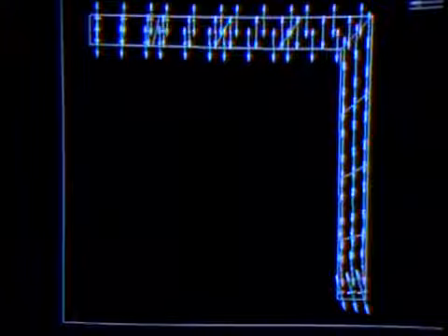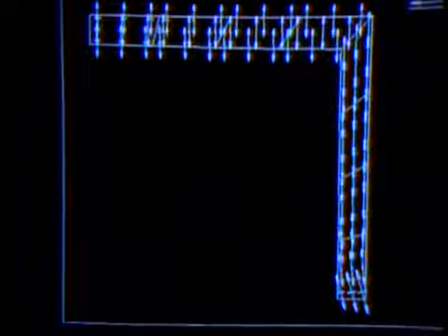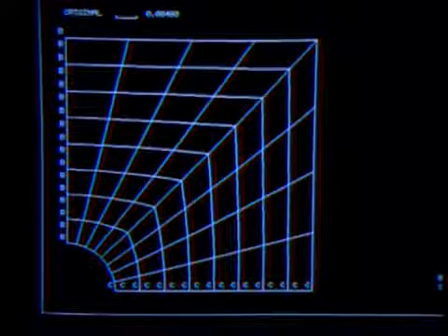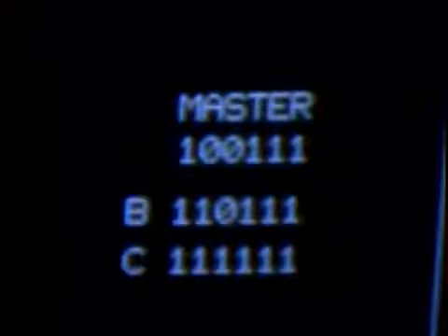Next, we show the stress vectors in the outermost elements of the quarter plate, and we can see here a stress acting perpendicular to the free edge of the plate when we look near the horizontal symmetry line. This is also unphysical and is due to having specified the wrong boundary conditions on the horizontal symmetry line. The specification of the boundary conditions is shown here. The character C denotes the boundary condition on the horizontal symmetry line. The character B denotes the boundary condition on the vertical symmetry line. Where B means only the Z displacement is free and C means all displacements are fixed.